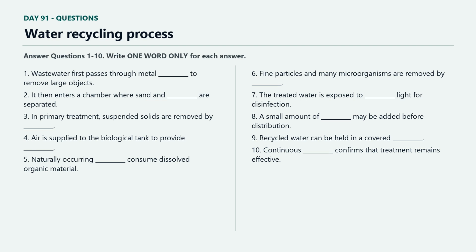The finished water can then enter a covered reservoir. Covering prevents birds, dust, sunlight, and surface runoff from contaminating the treated supply. Storage balances production with demand because the treatment plant may operate steadily while use changes during the day. Reservoir mixing is important. Stagnant zones can lose disinfectant and allow water quality to deteriorate.